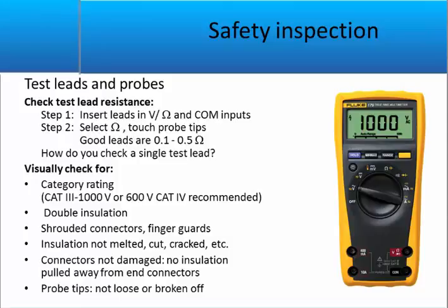Make sure that you have no damage to the lead. Make sure that it is good, both in the connectors, the terminal pins, as well as all the way through the insulation of the lead, and also at the tips. Make sure that they are not broken. A good way is to run your hand the full length of the lead and look for any abrasions, anomalies, or joints within the leads, because it will indicate at least a failure point in the future.